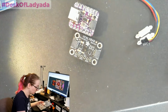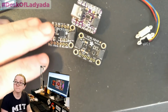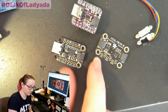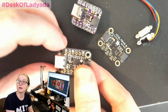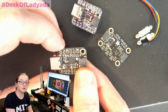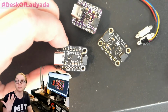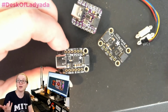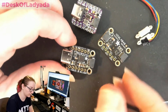Question: what do you think is the most elegant way to parse JSON serial data on a microcontroller? On Arduino, use ArduinoJson, and on CircuitPython you can just use string parsing or eval, since it's a dictionary. I'm going to vote for CircuitPython only because I've done a bunch of JSON parsing in CircuitPython. You can see it in the TV Begone project. I don't have a JSON parser that'll fit in a SAMD21, so it evals the file that contains the JSON, and it's fine. Nobody's going to root your chip, so who cares? It's like you wrote the code.